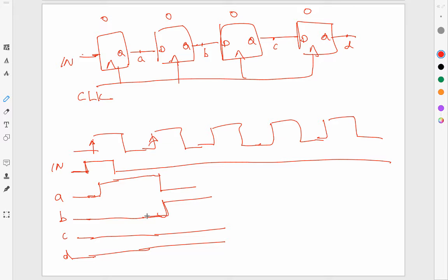Remember these changes are happening in parallel, so A is changing and B is changing. The reason is, as far as this second flip-flop is concerned, A is high at that clock tick, it hasn't yet gone to 0, and therefore it would capture a 1. In parallel, the first flip-flop is going to be making A 0, but both of those actions are happening after the clock tick. At the clock tick, this switch is happening.